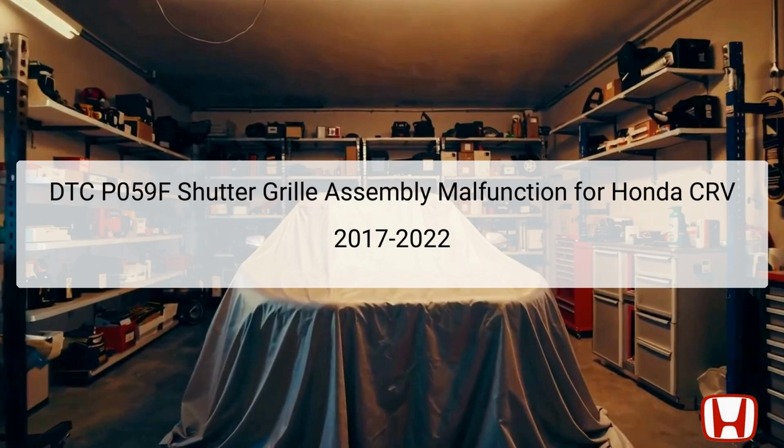The Diagnostic Trouble Code, DTC P059F, indicates a malfunction in the upper shutter grille assembly. The shutter grille assembly plays a crucial role in regulating airflow and enhancing the vehicle's aerodynamics, thus optimizing fuel efficiency. It is typically located at the front of the vehicle, just behind the front grille, and works in conjunction with the engine cooling system. The system is controlled by an actuator, which adjusts the position of the grille openings based on engine demand and environmental conditions.